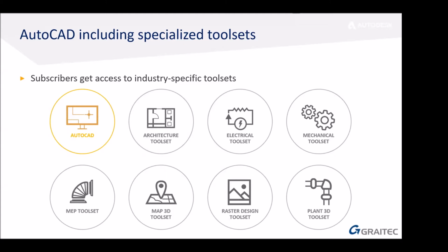So you'll know that you can open PDF files inside of AutoCAD and actually get all the layers through if it's a rasterized PDF. But you can also use the Raster Design toolset to rasterize PDFs that might just be lines that aren't on layers. So effectively, you can pull data out of them, or from a scanned image file, you can actually pull lines out and use that data again. So it's a really good way of getting data from old files or from drawings that have maybe been lost.